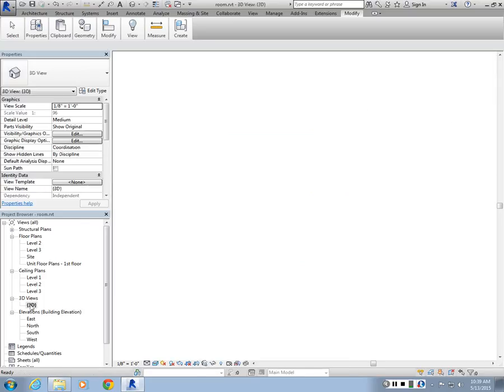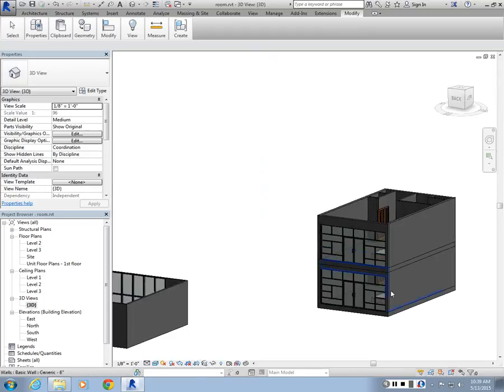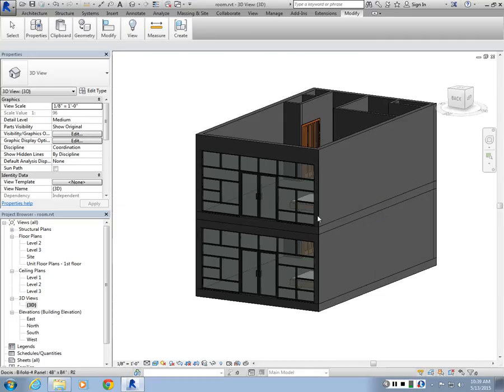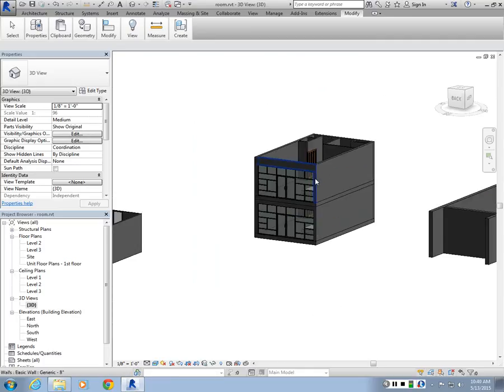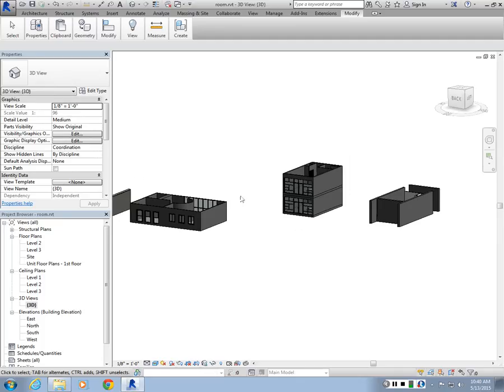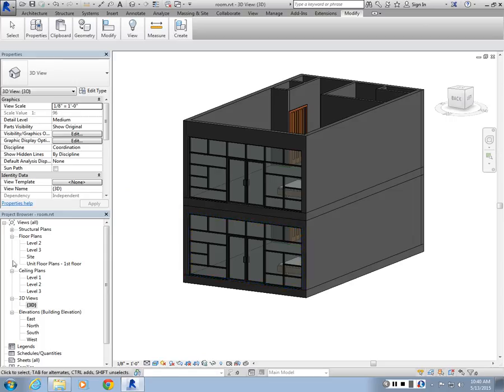And if I switch to 3D view now, there's a new floor added on top of the same thing. And I can do this operation multiple times, right? So I can create one floor with all the units I have, and then I can copy them to selected levels. So I can have like 5 levels, 6 levels, and I would have all of them vertically stacked. It's a really fast operation.